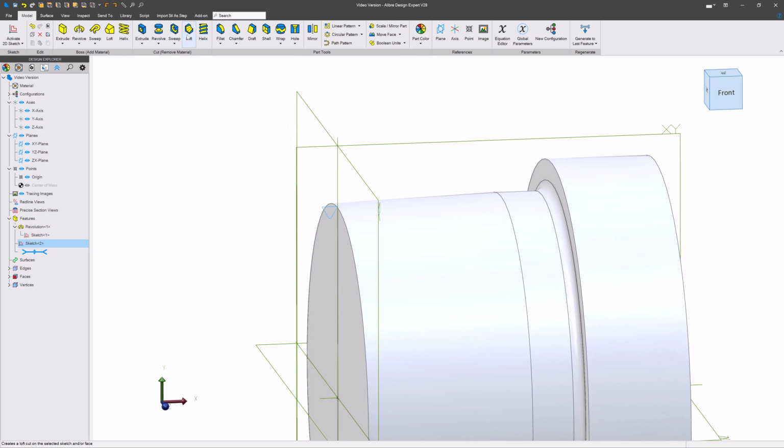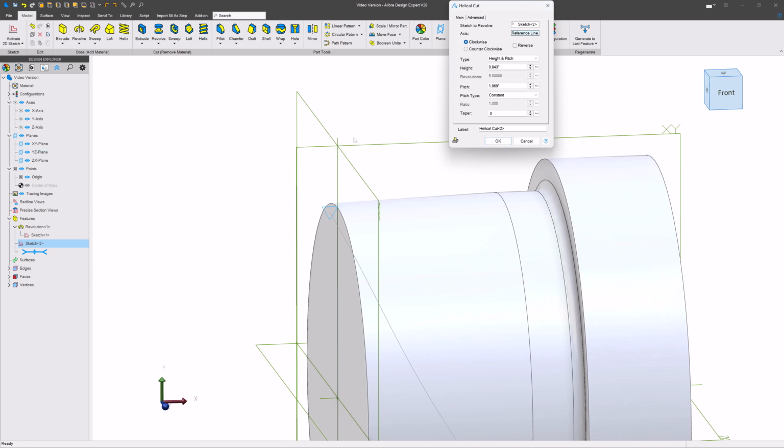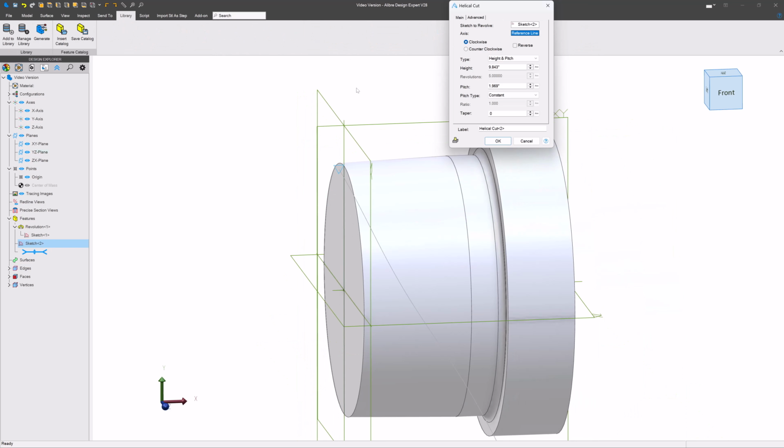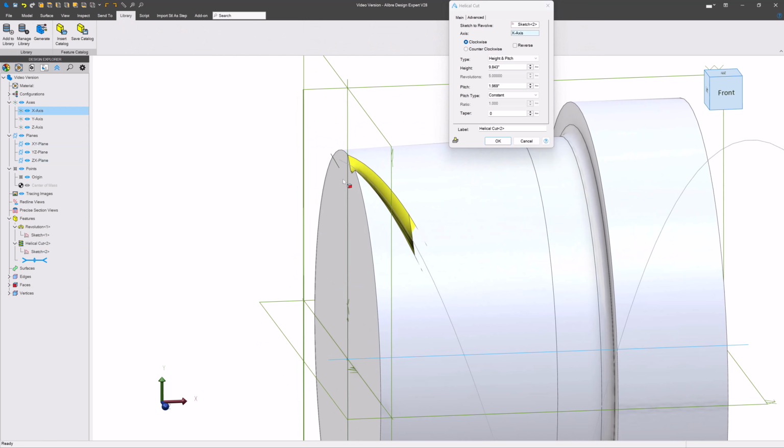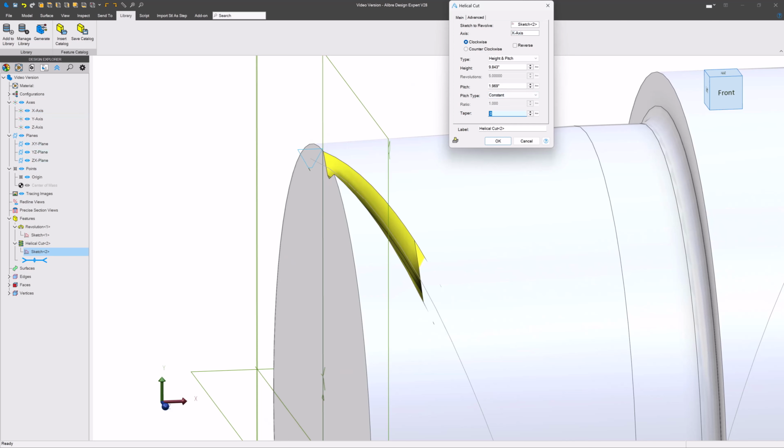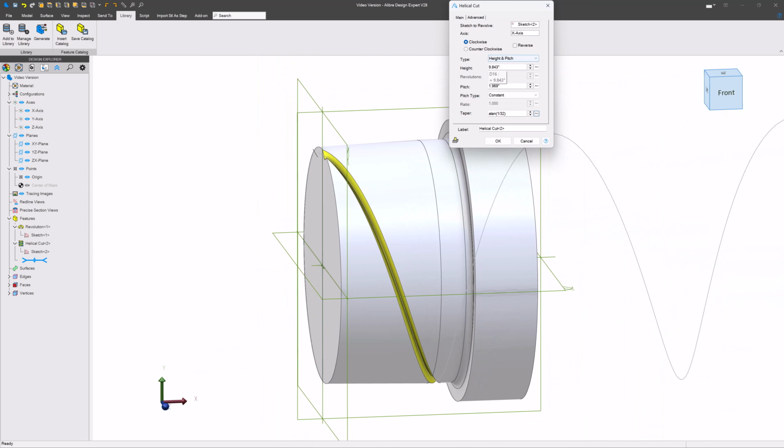And then we'll make a subtractive helix. Our subtractive helix is going to go around our axis, right? That little reference line right there. And we're going to define our taper. That's going to be an angle, of course. And again, a tan of 1/32. And when I give this the pitch, again, our pitch is pitch.